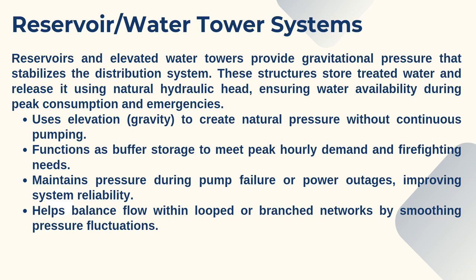Next is the reservoir or water tower system. The reservoir and elevated water tower provide the gravitational pressure that stabilizes the distribution system. The structure stores treated water and releases it using natural hydraulic head, ensuring water availability during peak consumption and emergencies, including use of elevation or gravity to create natural pressure without continuous pumping, and functioning as buffer storage to meet peak hourly demand and firefighting needs.